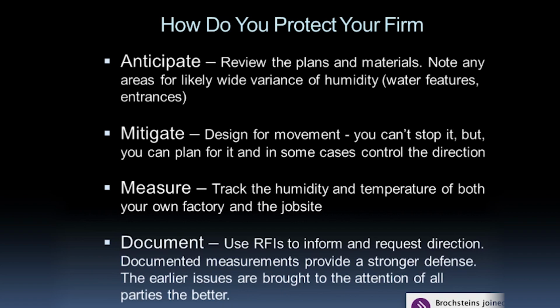We always do. Yeah, I think it's just a good practice. I was a consultant on a project out in Las Vegas, and they were sourcing doors for a big high-rise casino project. And those doors, it turned out, had about a 32% moisture content, which you should be around 8 to 12%, maybe a little bit drier out there, but 30% was way over the limit.